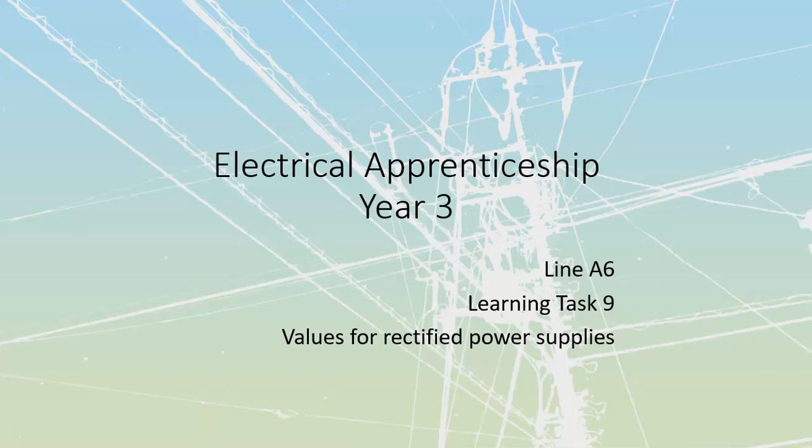Now some of you are saying, why are we looking at such massive values of DC? To be honest, there is a huge use of DC in heavy industry, particularly in chemical processing. There are so many electrochemical processes where we are going to use electrons to carry stuff, electroplating or taking stuff apart. You take a large saltwater brine, you heat it up, you hit it with a couple thousand volts of DC running through it, you're going to be able to separate that into hydrochloric acid and caustic soda, both of which are great industrial chemicals that have their uses for different stuff. You wouldn't want to touch either, but these are things that allow us to create and do a lot of the industrial systems that we need.